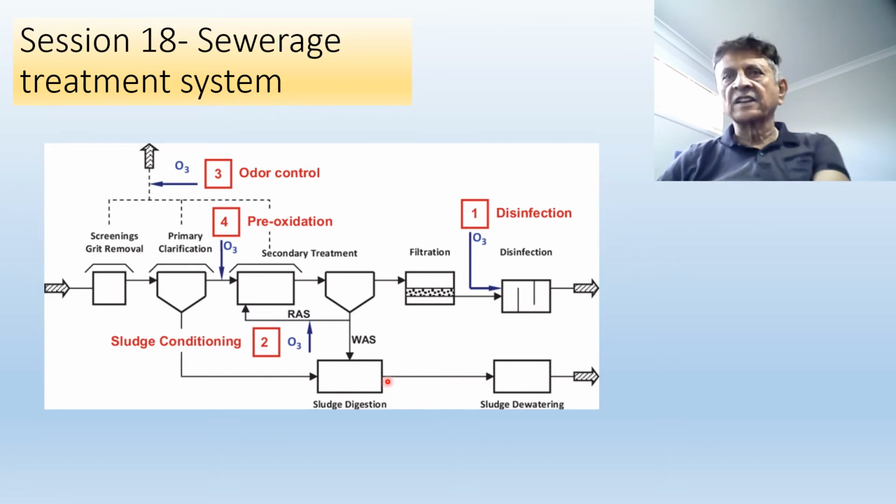For example, the digestion of the sludge can continue here, and the water removed from the sludge, or dewatering, the dry sludge is taken for further sterilization before it goes to the garden markets as fertilizers. The sludge water can be taken back to the pre-oxidation process or pre-ozonation process and continue towards filtration.